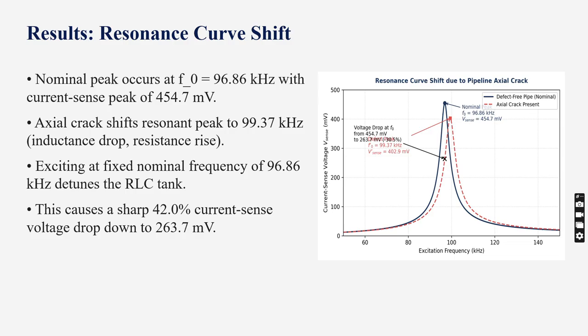Now let us examine the results. This figure shows the simulated current sense voltage curves. In the defect-free state, shown in dark blue, the resonant peak is at 96.86 kHz with a peak voltage of 454.7 millivolts.